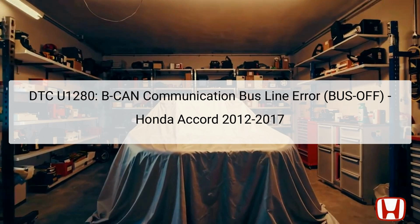In the Honda Accord model years 2012 through 2017, this error could affect components like the automatic lighting and rain sensor, which rely on this communication for proper functionality. The system assessment may involve checking connections and the integrity of the communication lines, since poor connections are a common cause of such DTCs. Correctly diagnosing and resolving this error is crucial for maintaining optimal vehicle performance and safety.